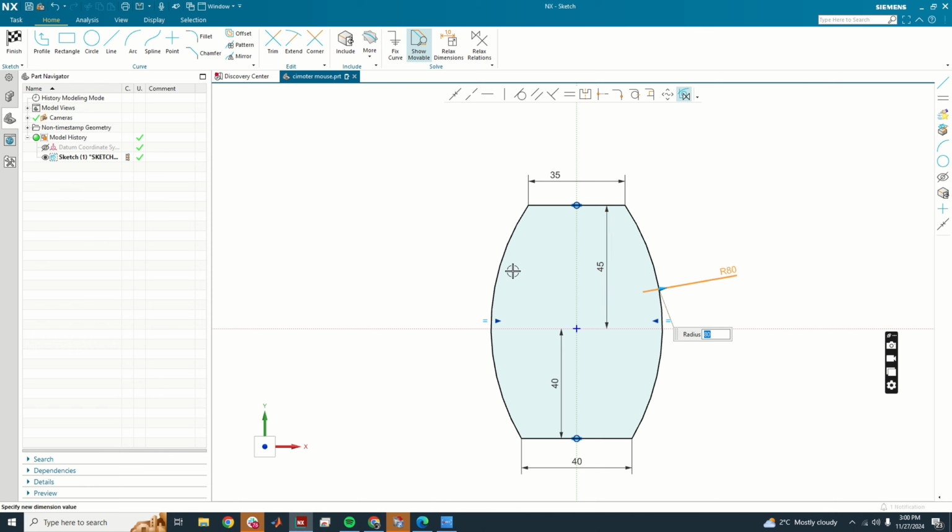This is a really simple scenario. And in cases that are this simple, it might actually be more efficient just to make two dimensions or just make them equal to each other. Because if I use this make equal constraint, that would also do the exact same thing I just did. But if you have a much larger, like if you have multiple lines, for example, that all needed to be mirrored onto the other side of your axis, this mirror constraint is a great way to do that. Anyway, let's move on from that.